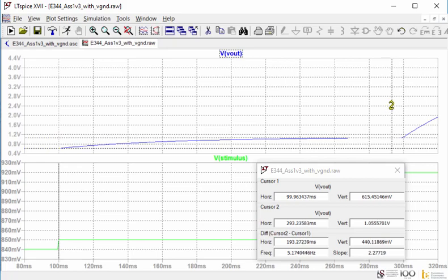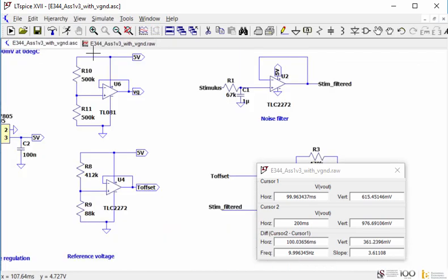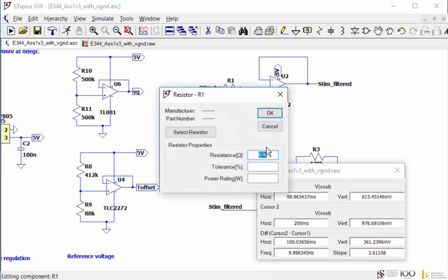So all I want to check is that it has reached 10% of the final value within 100 milliseconds. If I go back, has it reached 90% of that? And the answer is, if I consider that the final value is 440, what seems to be 442, let's make it 450 for argument's sake, you can obviously go and calculate or measure the total one after a few hundred milliseconds. It has reached 360. So that is not 90%. So that means that my filter is filtering too low. So this 2.5 or 2, whatever, 3 kilohertz that I have is too low.